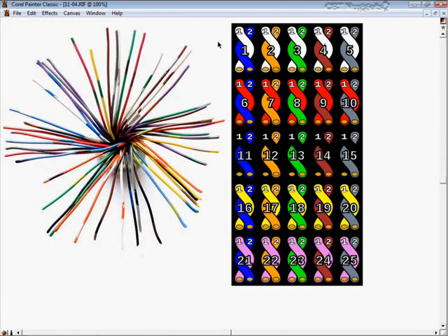The next concept that you want to know about for the exam is what's called 25 pair, the 25 pair color code. Don't worry, you don't have to memorize this, but you do want to know that the 25 pair color code is used to identify these conductors, these wires in your telecommunication wiring for indoor use. This is our twisted pair cable. You can see here there's a single core 25 pair 50 conductor cable that we're looking at right here. Here's a chart of how those twisted pairs can be grouped up. These can be used for common analog telephone service, as well as other twisted pair wiring conventions.